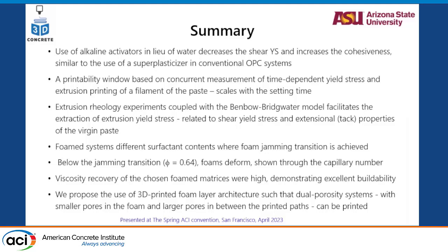We looked at a printability window. Extrusion rheology experiments coupled with a model get you the extrusion yield stress, which explains what happens in the system much better. Of course, foam systems, which I showed you. Once you get to the jamming transition, you can print them well. Not just print them well, you can print even lattices with them, which will give you extremely low thermal conductivity.